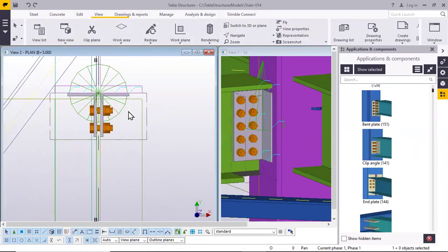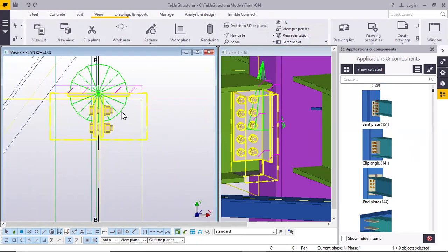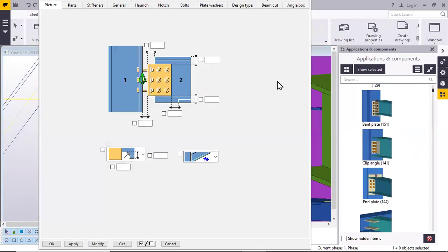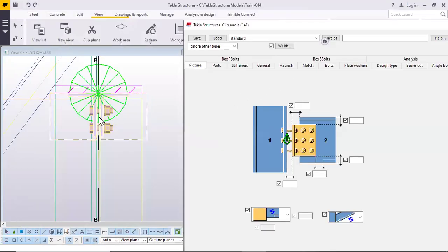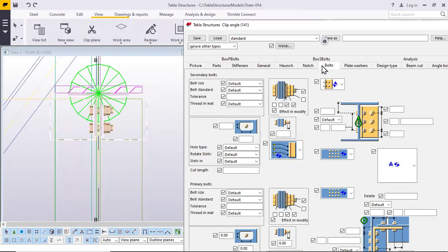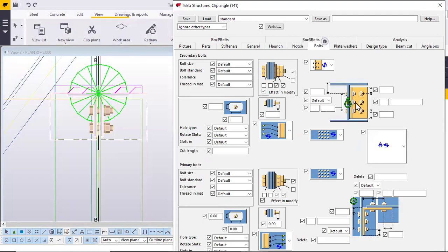A little bit complicated because an angle connection is there. So we have to play with different sizes of angle, and then bolting is also in a different way. Here there are two areas where we have to bolt. One is here, one is here. So when I go into the bolt, you will see a different interface here for bolt. You can see there is double.